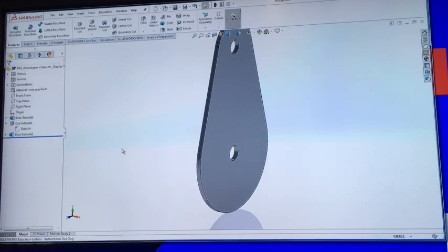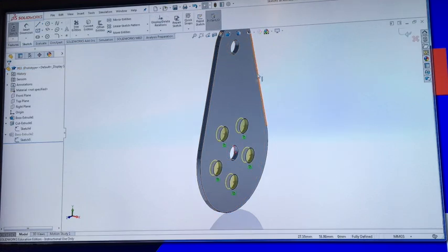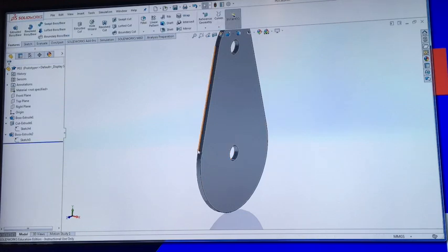Like that. That was quicker than I would have done it. Yeah, but that idea is spot on, right? Yeah. So if we want to fill in those areas and it's just a flat face, then we can do the sketch. So what I did was convert entities. So I selected sketch number 4, press convert. I deleted the sketch that had converted these 2 holes because I don't want to fill those in. And then I did a boss extrude, which goes up to that edge or that point.